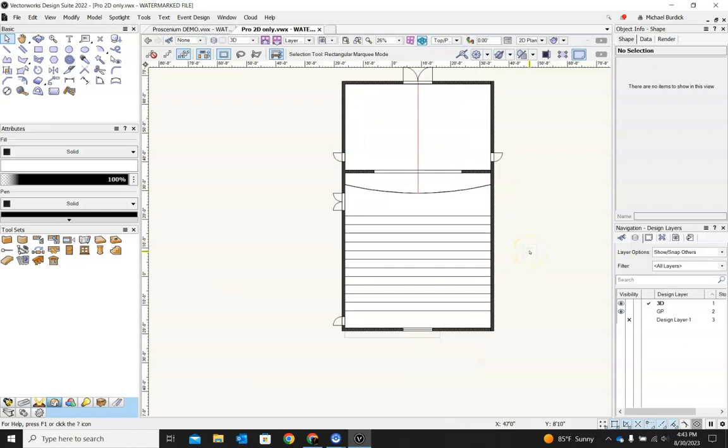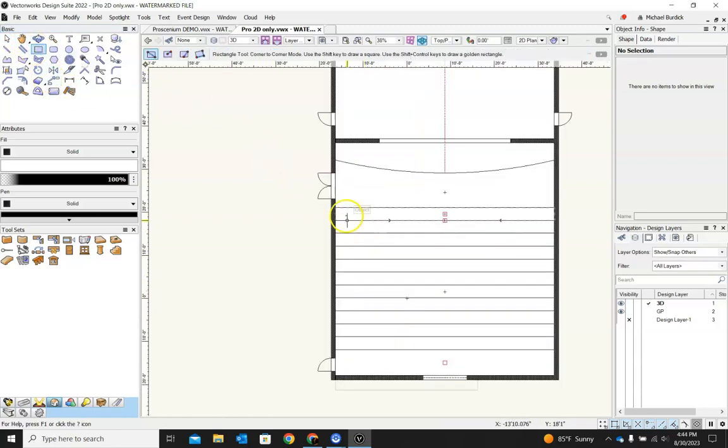The tricky part here is going to be having all of these different stairs coming up at different heights. There's a lot of different ways that you could do this, I suppose. You could select each one. You could draw out all of these different rectangles and extrude them, which would look like this.